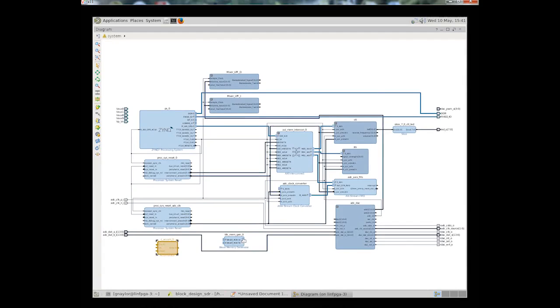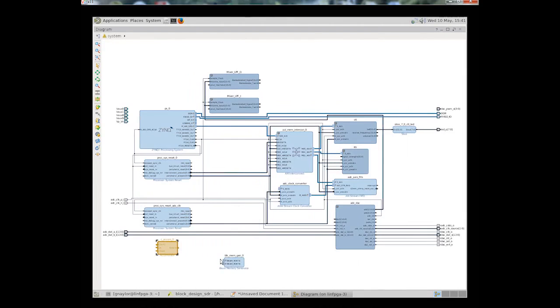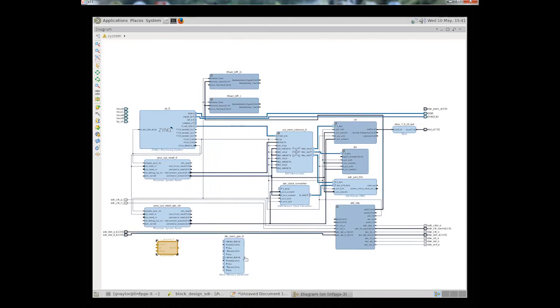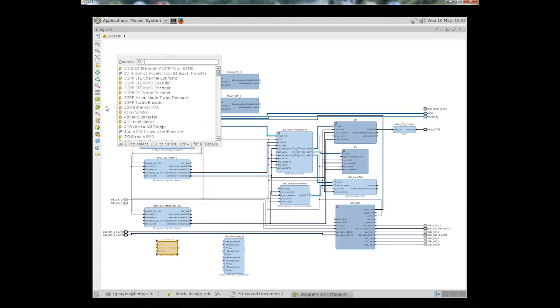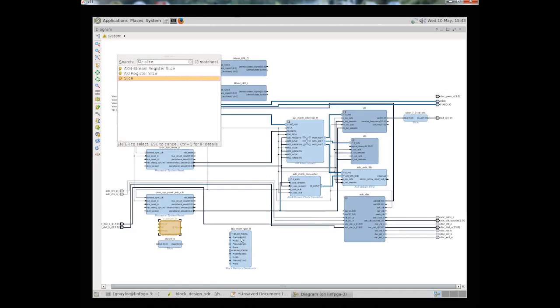But let's just carry on and finish off this local oscillator, because we want to drive this memory with two address inputs offset by a quarter period. So firstly we need to slice off the top 11 bits, 11 bits being required for the address bus of the memory.